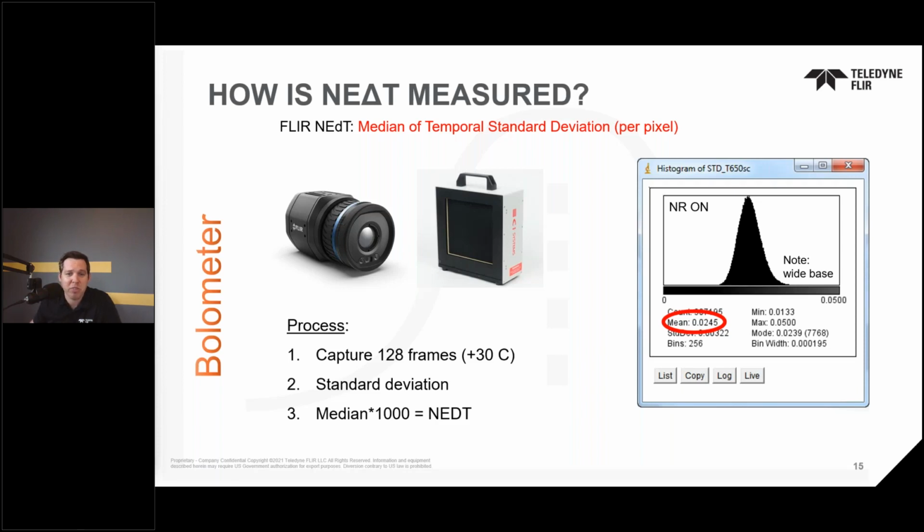We've just reviewed how each measurement is conducted, but again, the main takeaway is that changes in how the NEDT measurement is performed can really drastically affect the outcome. For example, if a spec sheet stated that the measurement was performed at 50 C and showed a similar sensitivity as a camera NEDT measured at 30 C, I'd really ask more questions about how that measurement was performed, and I'd really want to see the camera in action to properly compare.